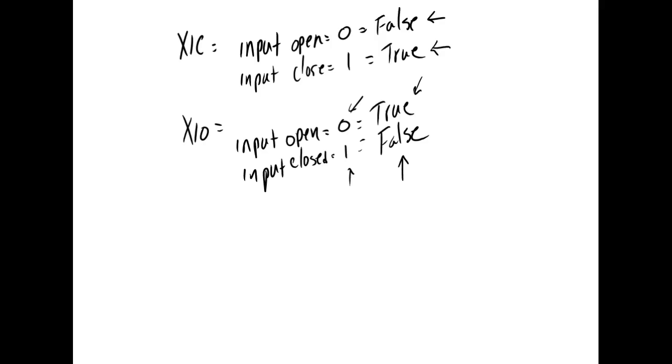Y'all know what the default in computers is. When you have an instruction that requires information, probably 90% of the time the operating system sticks something in there by default. Default means what it uses if you don't change it. That's what a default is. So every PLC that I've ever dealt with defaults to examine close, and you have to change it to examine open. E-stop is already automatically examine close.